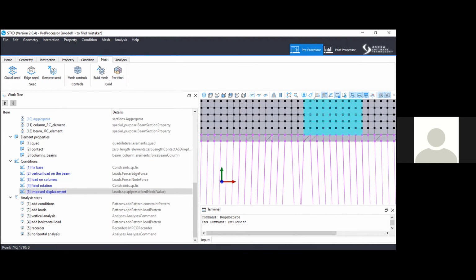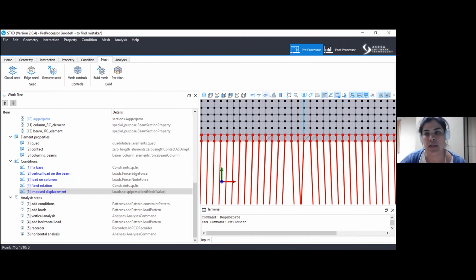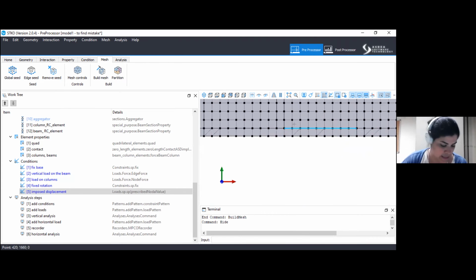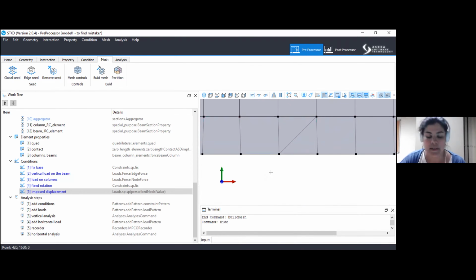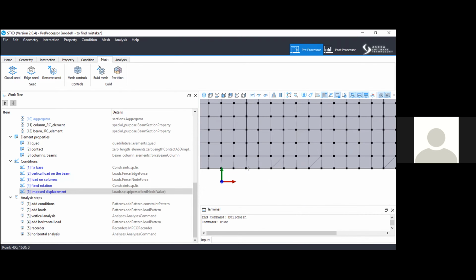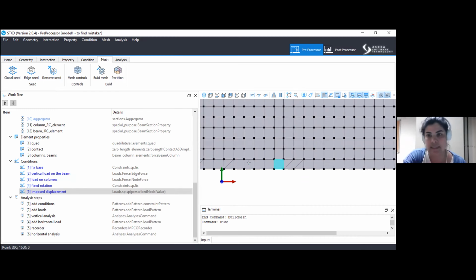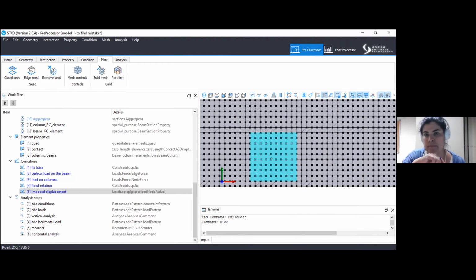And then there is one that is in-plane analysis of masonry walls, micro and macro modeling. There he explains the other way of doing it. So it's not using the master and slave, but using an imposed displacement. And for me, because I'm modeling something similar to this, this way was better.